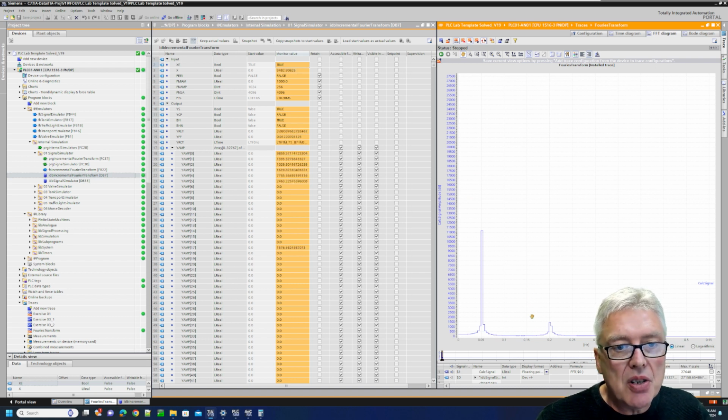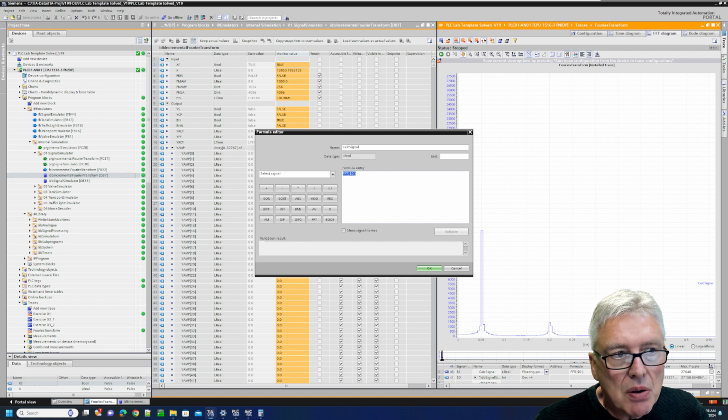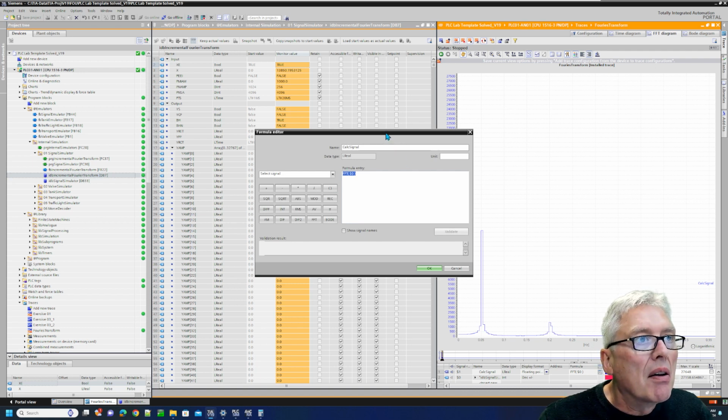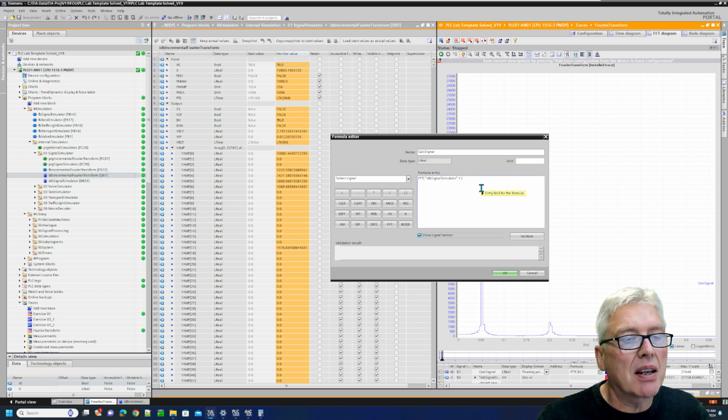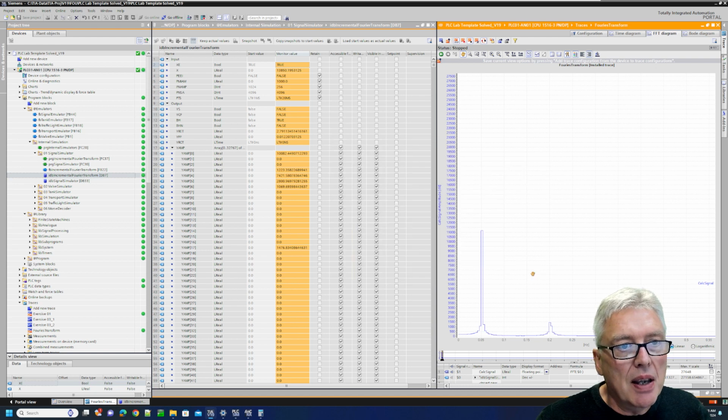Maybe we can have a look at it now. What you do is add this FFT from the help file. There are probably some more arguments you can have here too, and you can show the signal. So this is the output of my signal simulator that's running on a 5 millisecond interrupt. Here you can analyze the signal. Here are two sines and some random noise.